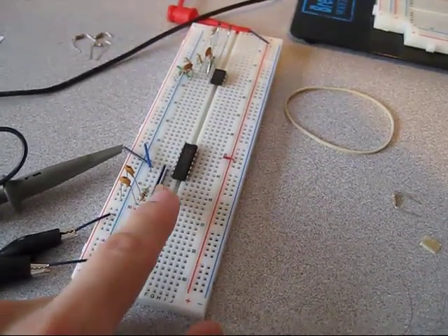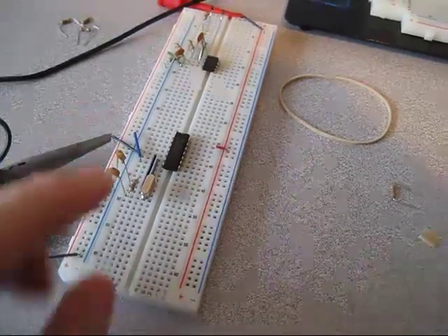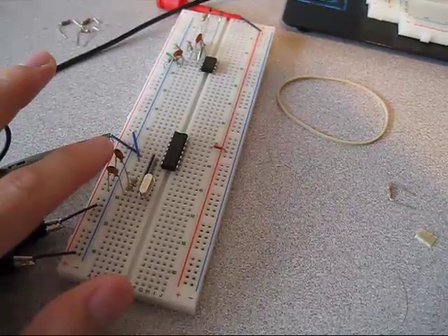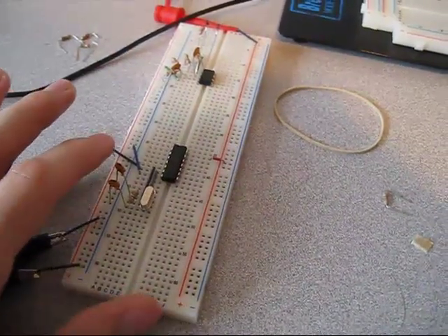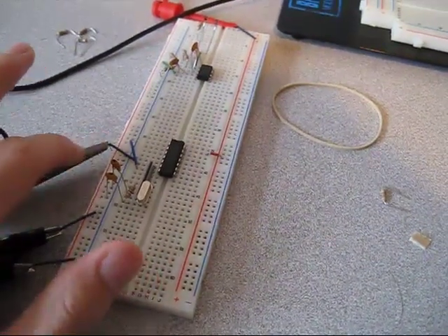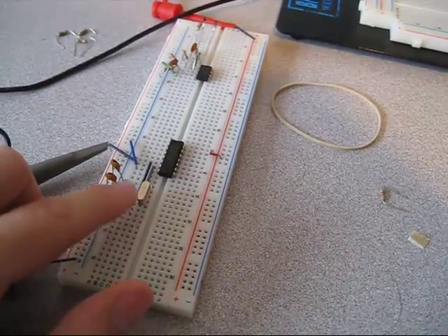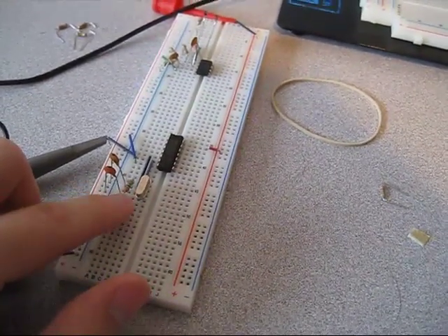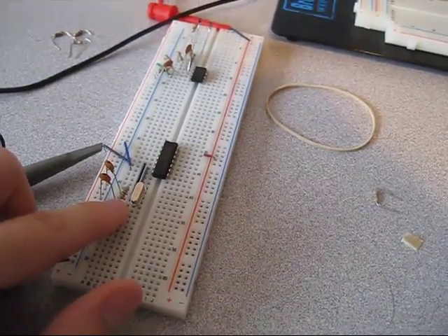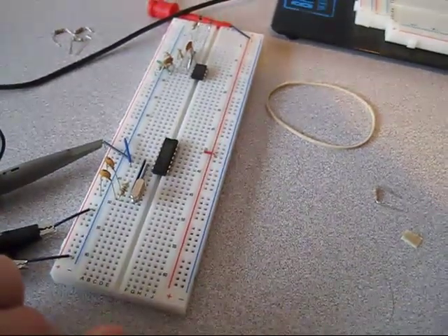So what we've got is just a 20 megahertz crystal, and I grabbed some close enough capacitors here. It's just whatever I had conveniently nearby, and these are both 22 picofarads. And what we're going to do is look at the output, and our feedback resistor here is a 1 mega ohm resistor. So if you're looking online, most of the time they'll suggest 10 mega ohms, but I actually don't have any around, so we're going to go with the 1 meg.